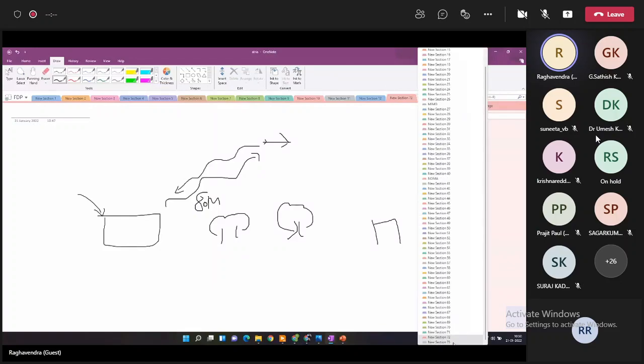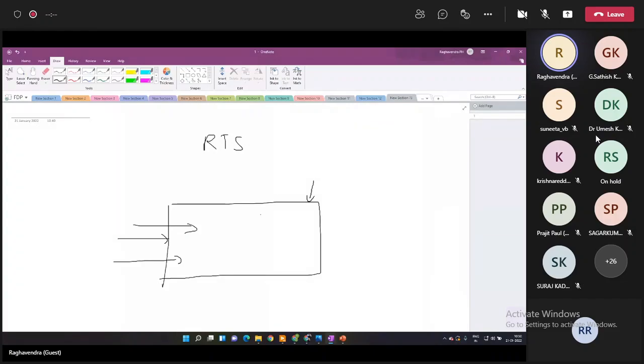So in all those cases, what you do is you have a hardware called a radar target simulator, where you will be able to code any situation into the target simulator. You give the signal to the target simulator and you take it out from there. Let's say I am telling the target simulator, okay, fine, I want the signal to bounce off an airplane that's supposed to be 70 kilometers away.